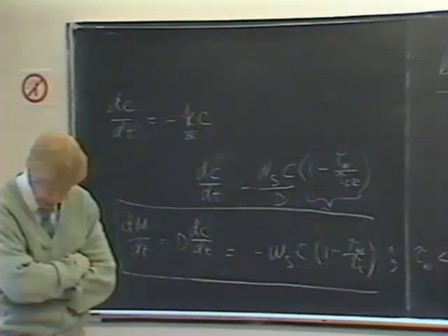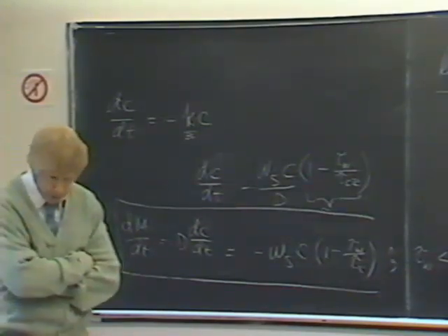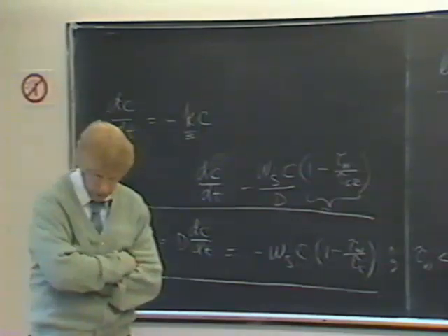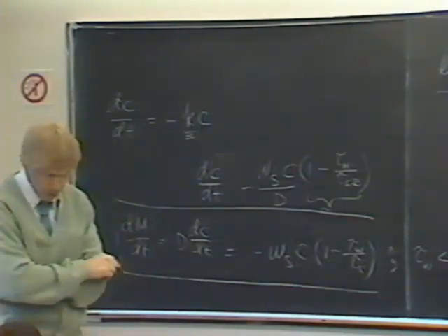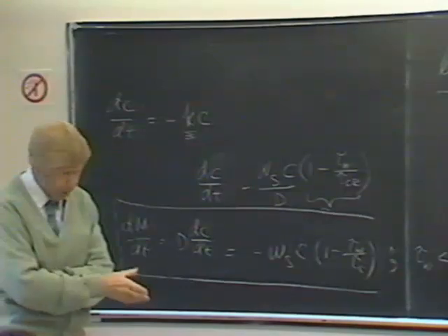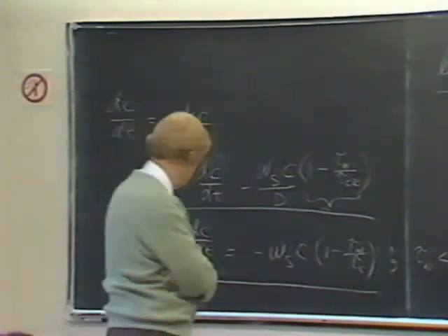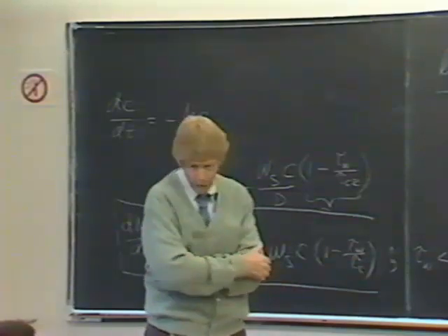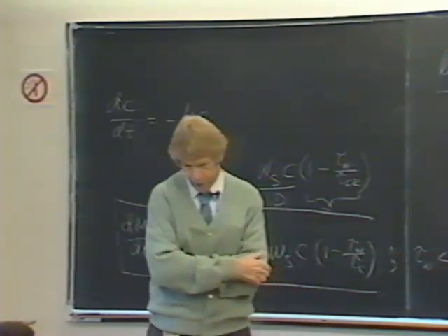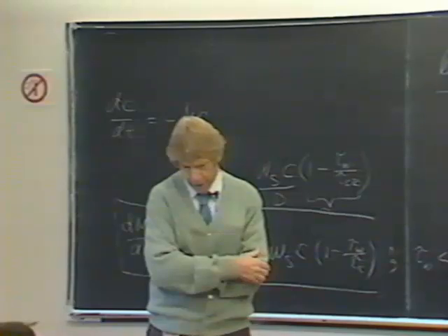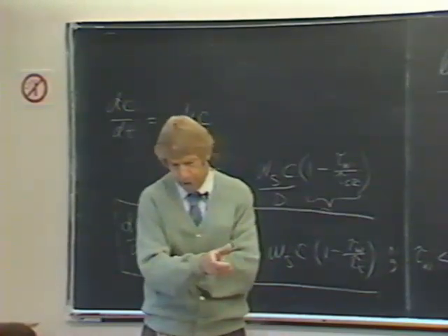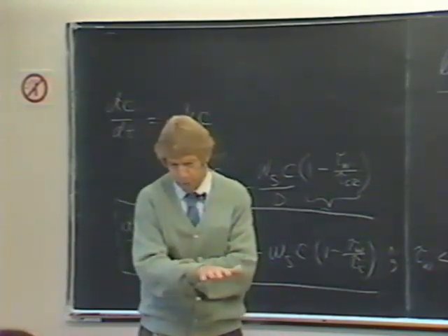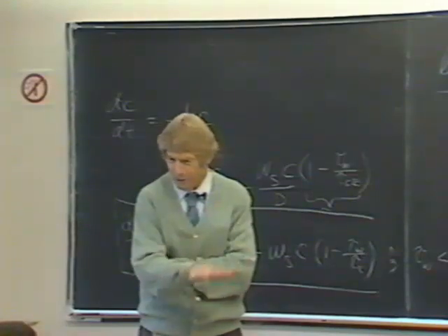Question? Do you have a distribution along the flume of the thickness of the particles that were deposited? It would seem like the pump would shear all the particles back to some consistent size, and then they'd come into the flume, and it would take a while before they'd aggregate to a size large enough to settle, so you'd go a little ways down the flume, and then you'd start getting... In fact, it appears that the pump didn't break them up.